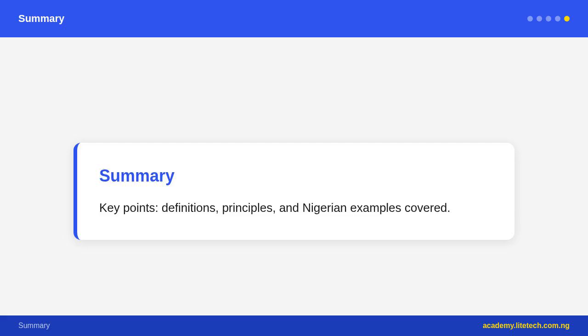Smoothing. A large capacitor is connected in parallel with the load, it charges during the peaks and discharges between peaks, smoothing the pulsating DC to a more constant level. The ripple voltage is the residual AC fluctuation after smoothing.